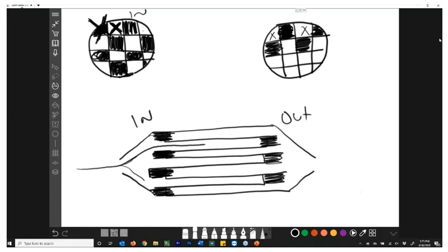When it goes to this open chamber, it continues down this chamber, and it basically hits a brick wall. It stops. There's nowhere for it to go, except there is. Because what happens is it stops here, but each one of these walls is going to be porous. This means they're a wall flow filter. It's not a direct pass-through, it's a wall flow. So once the exhaust gas hits this wall here, it will redirect through this media and then come out.